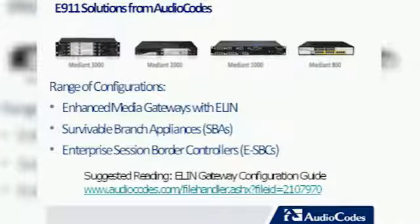So a question that pops up often is, what are the devices that support this functionality from AudioCodes? It's the range of our digital gateways, from our smallest little Mediant 800 on the right with a single T1 or E1 span, up to the Mediant 1000 with up to 4 spans, the 2000 with up to 16 T1 or E1 spans, and the Mediant 3000 with its N+1 redundancy, supporting 3 DS3s. So a very, very broad range of our digital gateways support this functionality.